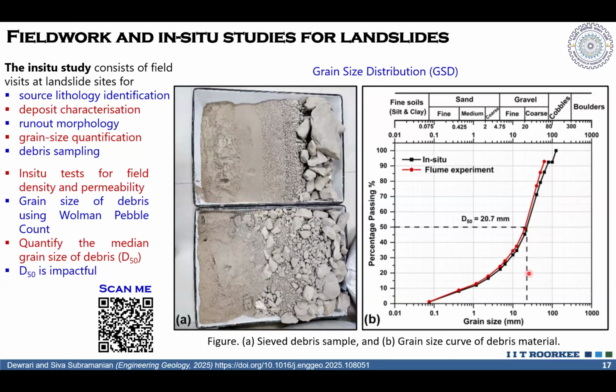We do have a typical limitation in our lab because we are using conventional geotechnical equipment, where for triaxial testing, of course, only grains less than 5 millimeters can be accounted for, and we can do the direct shear test in dry conditions only, to know the shear strength of the material, that is cohesion and angle of internal friction. So what we did is we transported something like 2 tons of sample from the debris slide. We visited the site only after the failure and transported that material.